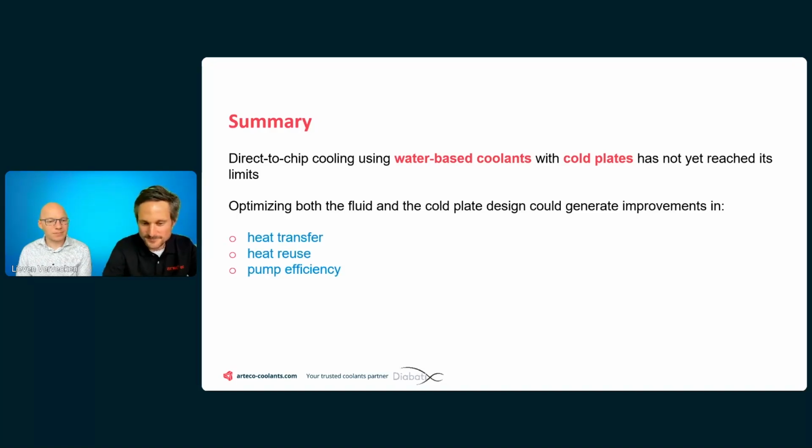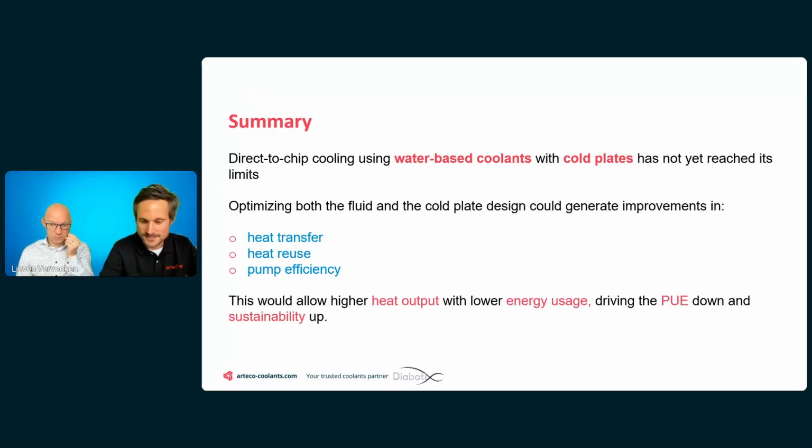By optimizing both the fluid and the hardware, the cold plate design, we can generate improvements in the heat transfer on one hand, but also in the heat reuse and also on the pump efficiency level. And this will allow a higher output with a lower energy usage, driving the PUE down and the sustainability eventually up.